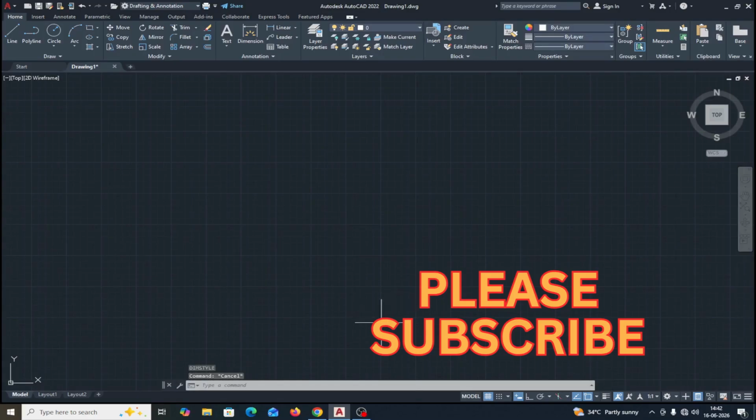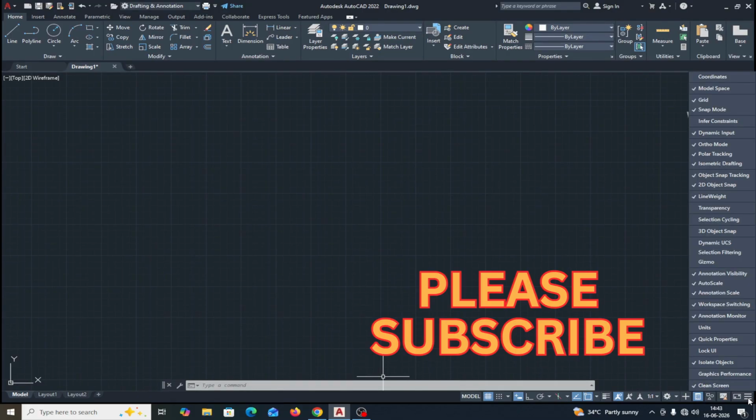Hello everyone. In this exercise of AutoCAD, we will understand how to move an object to specific coordinates. First, we will have to make some settings here. This is the status bar. There is a dynamic input button. If you don't have this button, you can go to this corner, the 3 lines, and customize it.